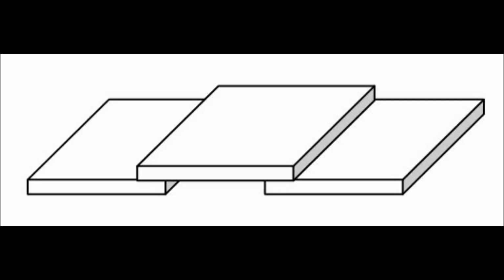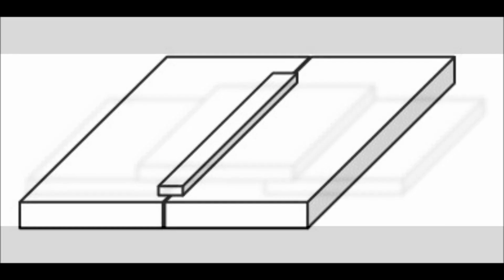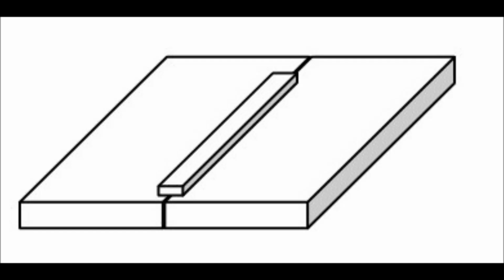One can achieve this in several ways. One is to overlap. Two edges of shield material can overlap 1 to 2 inches typically. Compression such as between layers of drywall or plywood will help to make good metal-to-metal contact. Second is tape. Two edges can be butt joined, then use a high permeability tape such as joint shield to tape the joint. Naturally, the shield pieces should be adequately fixed in place by mechanical means to avoid separation of